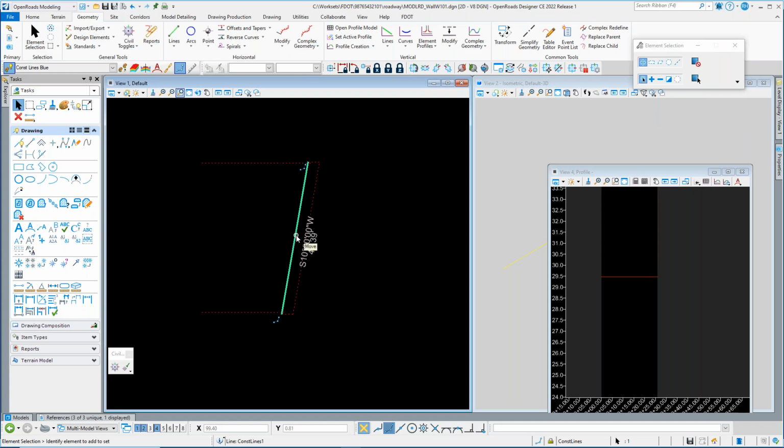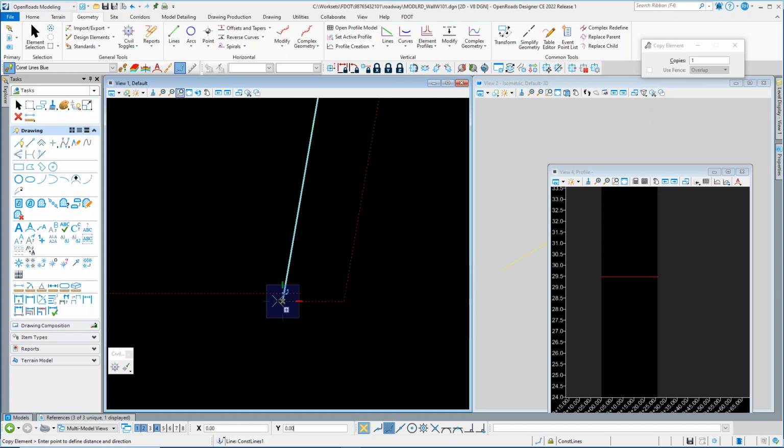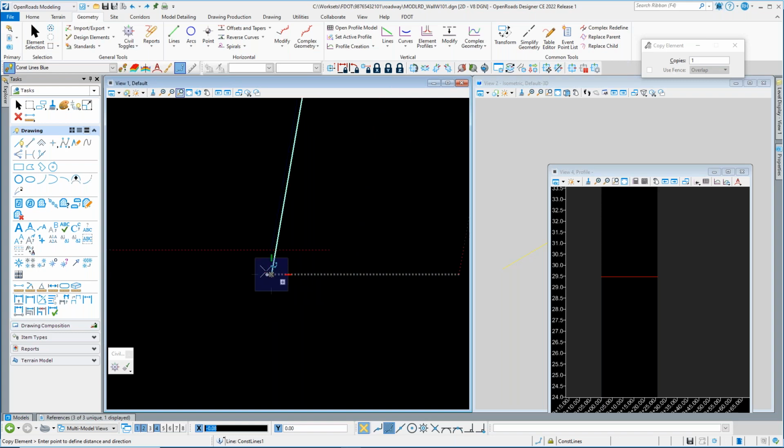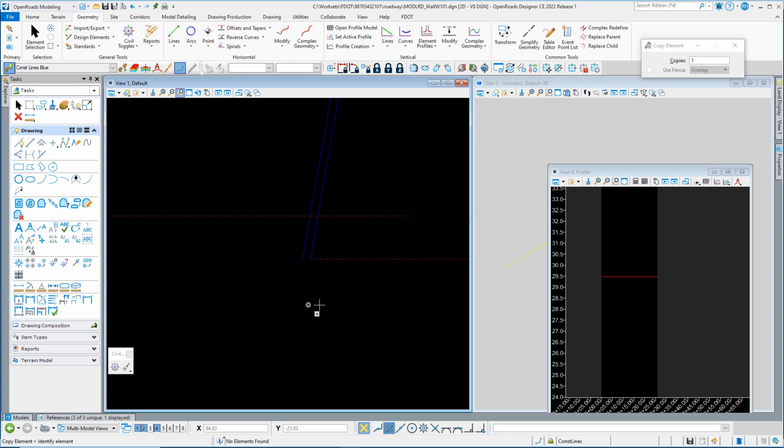So we've placed our new line here, and we're going to go ahead and just remove the rule from this so we can make some changes to it. We're actually going to copy this to get our 1 inch offset from our back wall. And I like to use AccuDraw on this. So what I've done is I selected it, and then we're going to copy it out. So we'll lock out AccuDraw, and it's hard to see, but it's 1 inch, copying that off 1 inch.